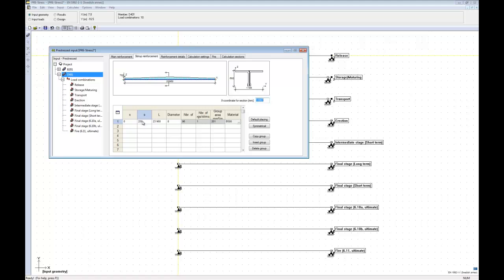But in this case, if they have one leg here and then they are bent up backwards behind the other, and they have a spacing of 250, we might want to add 125, so we have the correct area here as well, in square millimeter per meter.